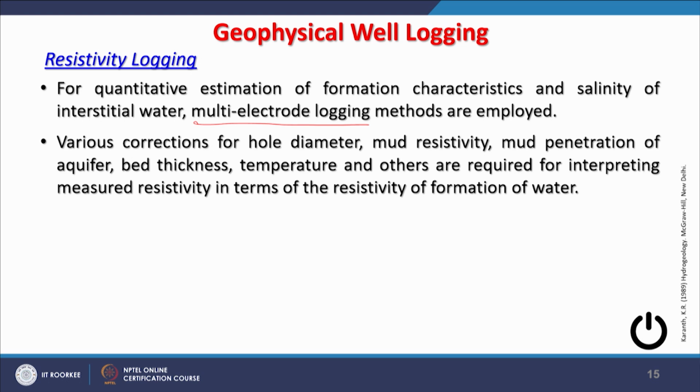Mud resistivity, since some places will have more mud and some less, mud penetration of the aquifer, meaning how much mud has gone inside the aquifer, bed thickness, the thickness of different formations encountered in a well, temperature of water, and others are required for interpreting measured resistivity in terms of resistivity of formation waters. How the resistivity varies in water rich formations and in formations without water will give you a lot of information, including your water table information.